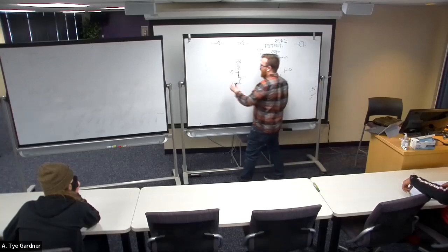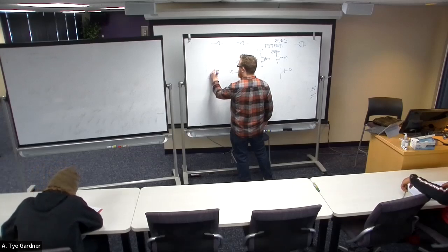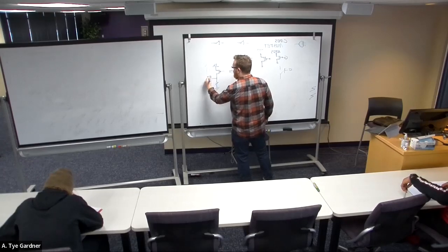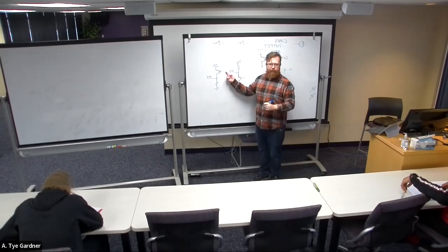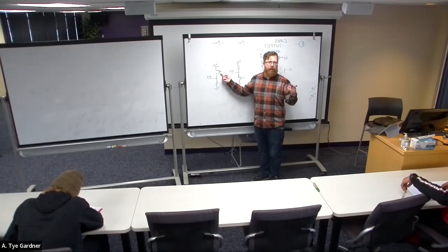And the PMOS, I can build the opposite way. Like so. So if I put a 0 here, that means the PMOS closes, meaning it is connected between the terminals, because the PMOS operates the opposite of the NMOS, right?